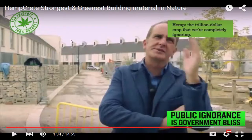If you take a look back here, you can see the convective gradient, the stacks that they've got set up here to cause draft, which if you couple that with the geothermal aspect, medium temperature, you can induce a draft through a subterranean earth berm. As heat is created in the building, that convective gradient causes a draft, and so it exits at the top, and cold air comes in, or hot air comes in and gets cooled.